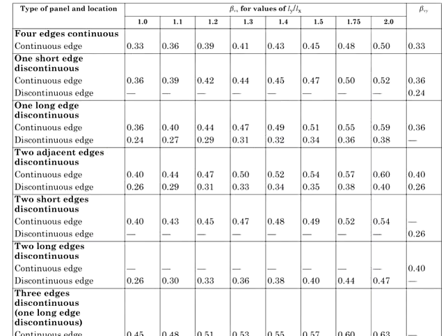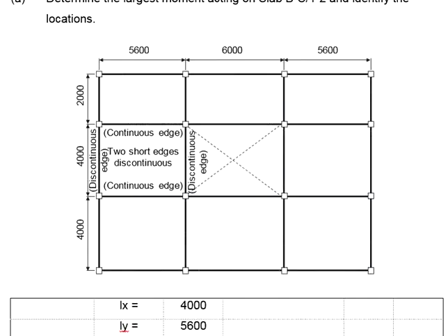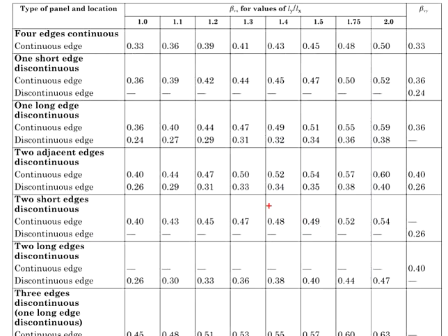Now, how do you define which edge is shorter span and which edge is longer span? When we talk about the shorter span, we are referring to the cut sections of the slab. When you cut the sections and view from the side, you will see the shear force diagram something like this. As for the longer span, you cut these sections and then draw the shear force diagram. It will appear something like this. So the coefficients given here represent the shear force on that particular section.